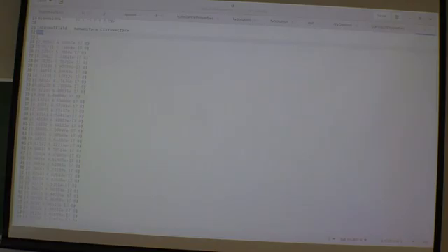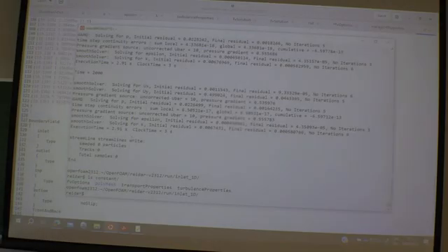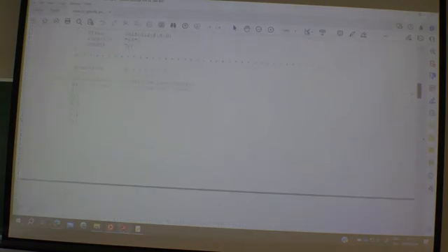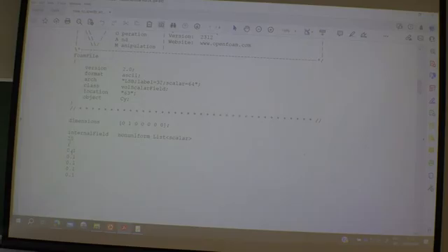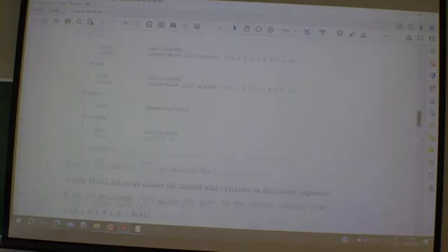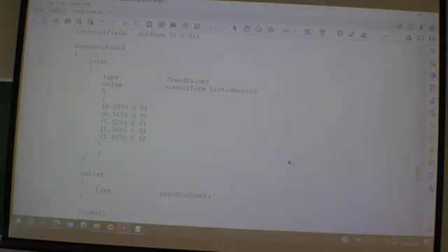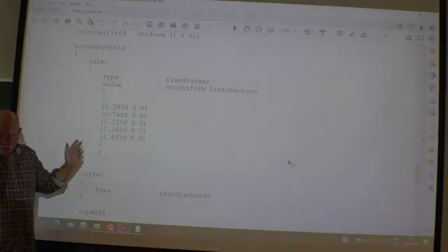Then you have to copy all of them and then glue it in as an inlet in your program. The same way I showed you earlier, the way we did it up here. So as an inlet in U, for instance, you just glue in the number of points that you have. No, not that one. Where was it? Here. Then you have to glue in your velocity components, and in the K file you have a K profile, and so on and so forth.